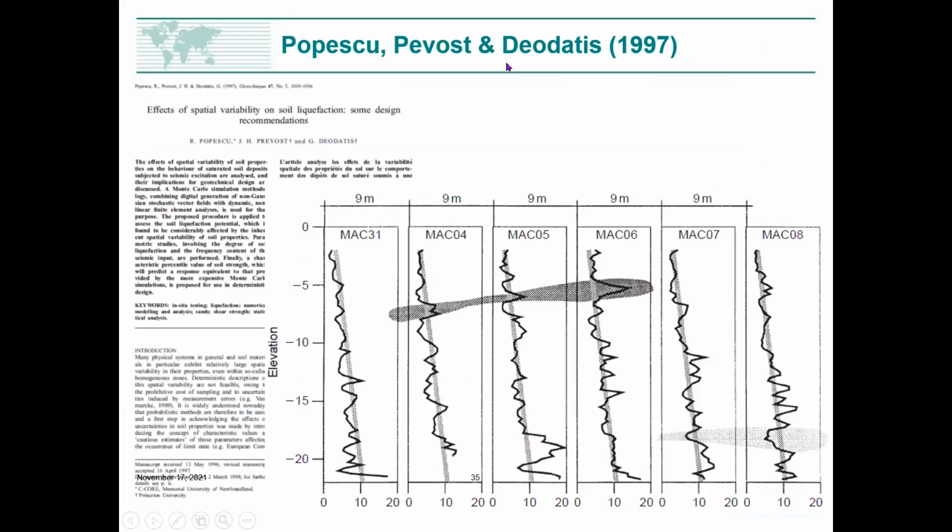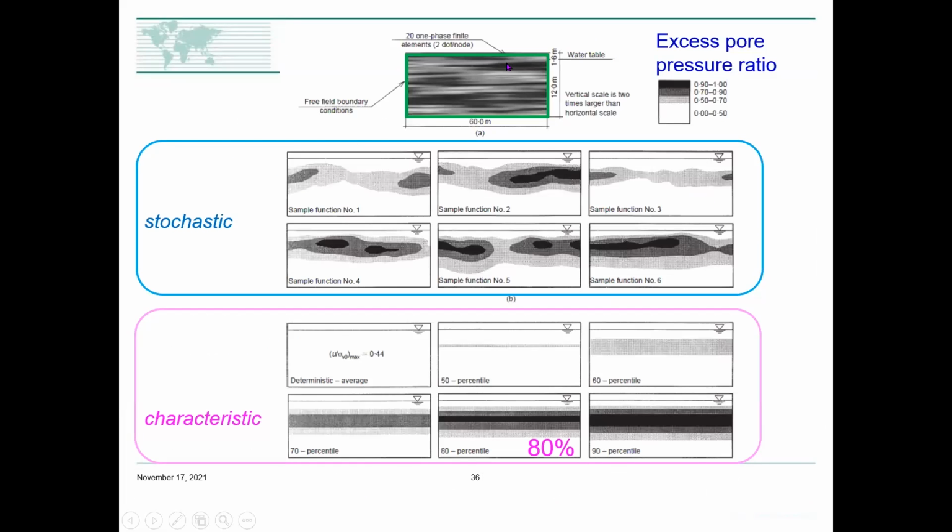distribution of loose and dense zones you see over here, except we made it a continuous function. So the dark is the more dilatant material. The white is the more contractive material. So this is an example of what they've implemented in their finite element model. So we've got complete variation of soil density across the mesh and with depth. And we've picked up an arrangement of things. Now, what they've then done, and that's called a stochastic model, they've then run the earthquake into that model.